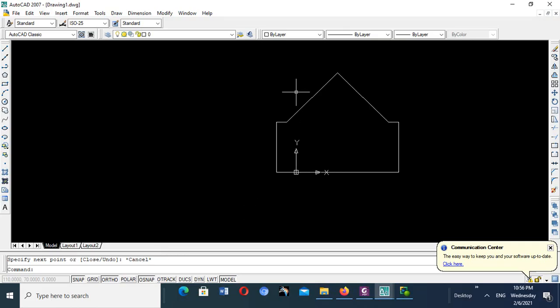I've used the line command where I knew the coordinates, so I can just use auto coordinates, or I also drew using a polar line where I know the angle of the line and the length of the line. So if I click the start point, then I mention the length of the line and also the angle of the line, I end up with a shape like that.